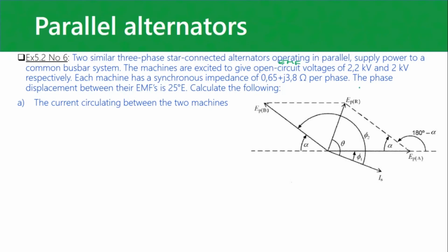You see, they didn't say line voltage. It is line voltage because they didn't say. If they say phase voltage, be careful, eh? Sometimes they tell you it's already a phase voltage. Now, don't go and convert it again and divide it by √3. And funny enough, we were doing this in class today, and people didn't see this is a three-phase, right?